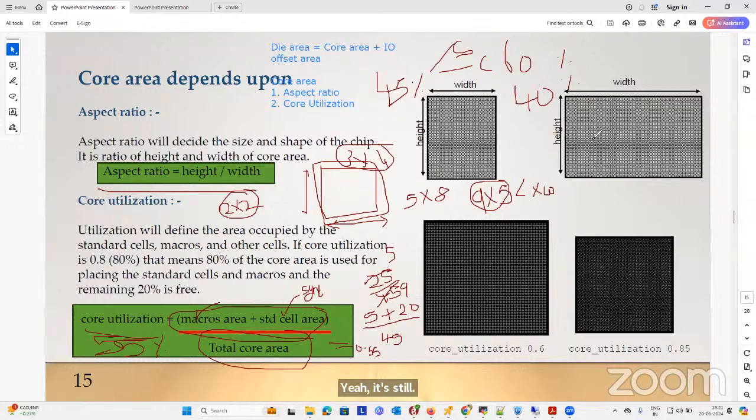If the routing and clock nets need more than 40%, we may face some issues. What are those issues? We'll learn in the next slides. We will get routing congestion, minimum space violations, shorts, breaks of nets, and antenna violations. All these violations come in the chip if the routing and clock tree synthesis is more than 40% utilization.